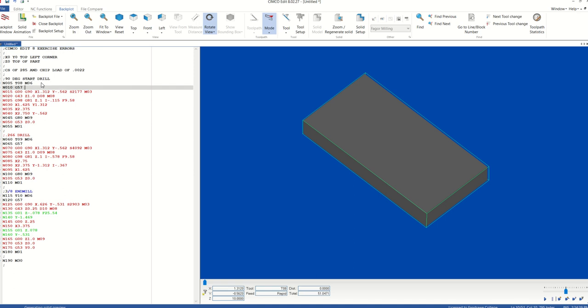And this is really nice. I can just use my arrow keys to come down. So here I am, I'm moving to this position. My tool is coming 1 inch above. I'm reading my height offset. I drill my very first hole, and then you can see on this command line here, again, all I'm using is the arrow keys on my keyboard right now to physically go through every command line one line at a time. You can see that my tool is heading in the wrong direction.